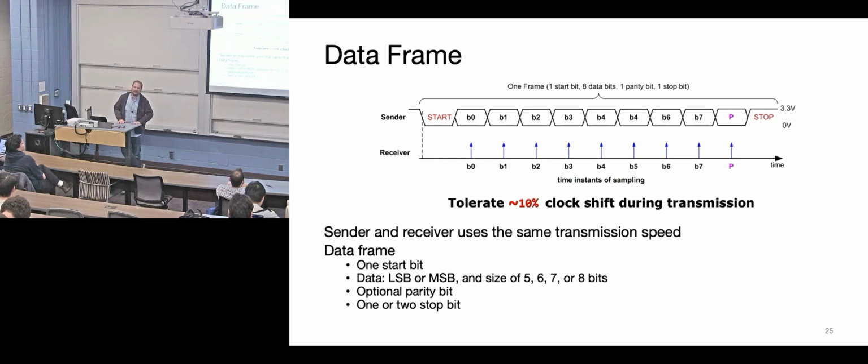Yeah. What is a parity bit? Parity bit is the most basic way of possibly understanding if your data has been corrupted. It doesn't help you correct it, it just is an indicator that something's different. So if I remember correctly, for a parity bit you count up all the ones, how many of those bits are 1, and then you say it's a 1 if there's an odd number, or 0 if it's an even number. And your hardware actually has a parity checker built into it, and it goes through and just counts up all the ones for you and says, is the parity bit correct? If the parity bit's incorrect, one of those bits got flipped, but you don't know which one.